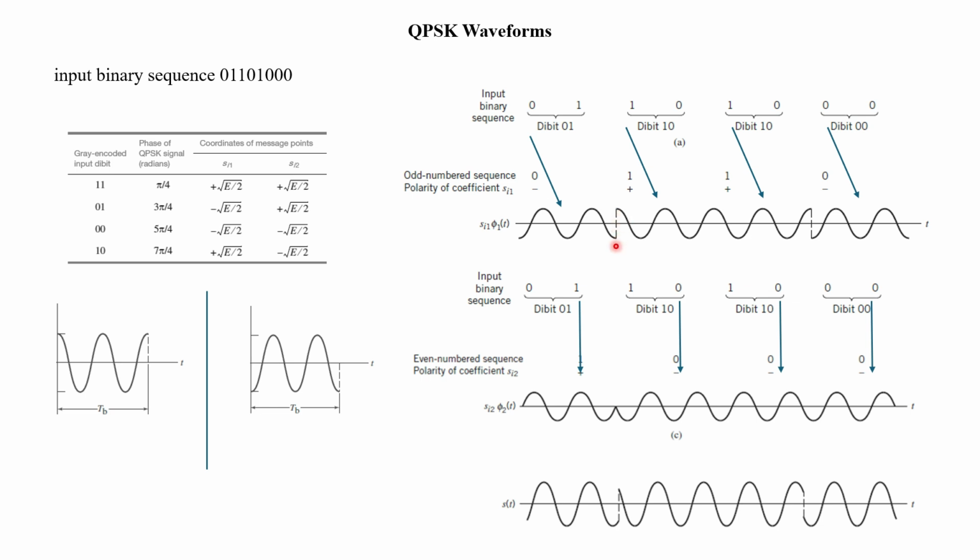And we'll check what is the phase at this zero crossing. Here the phase is negative, here the phase is 0. Therefore, 0 plus negative is negative. So like that, we can write the phases at the crossings. That indicates the quadrature phase shift waveform here.